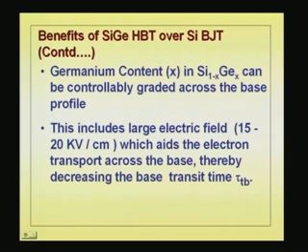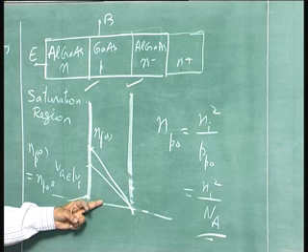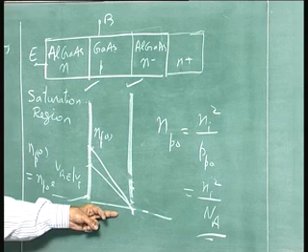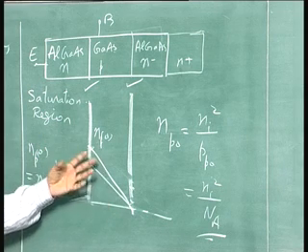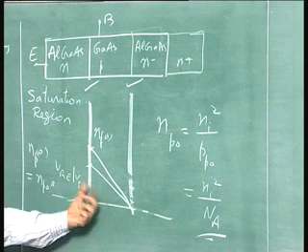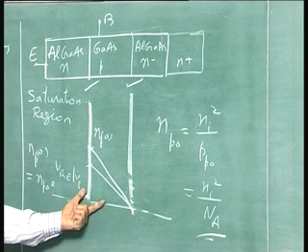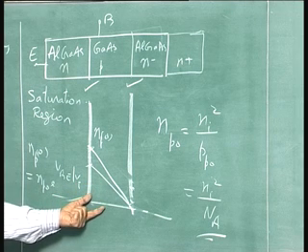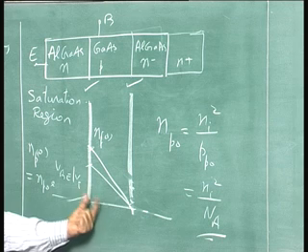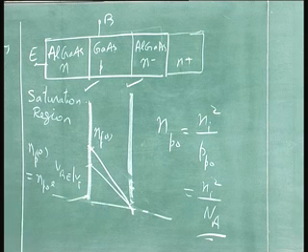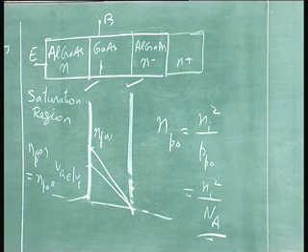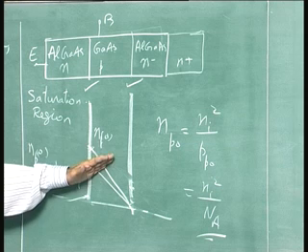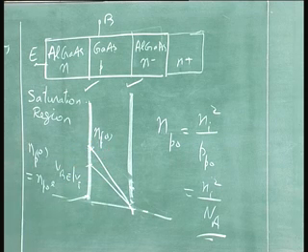You remember, when I draw a diagram like this, the carrier concentration is linear, varying injected carrier concentration. What we are assuming is the carrier transport is through diffusion. There is no electric field here, and the transit time is W squared by 2Dn. You can increase the speed or reduce the transit time not only by reducing W, if I can bring in electric field, the transport will be faster. The velocity by diffusion is smaller compared to velocity by drift. So, if I introduce drift by some means, I am in business. I can increase the speed, transit time can reduce by a factor of 5, 10.